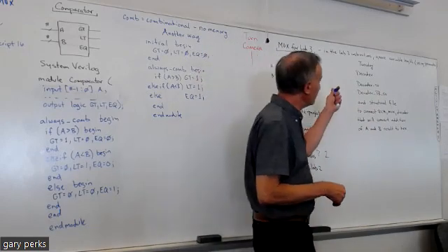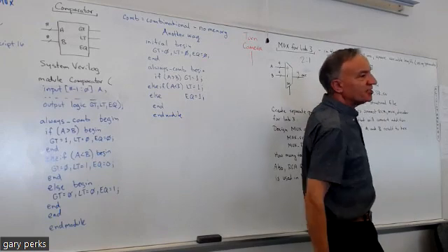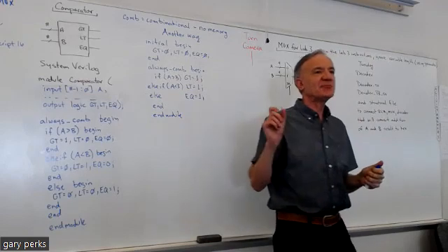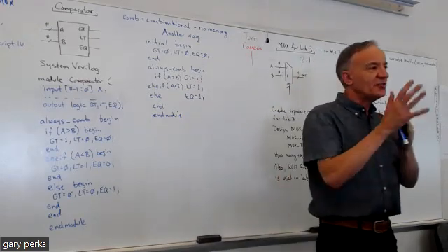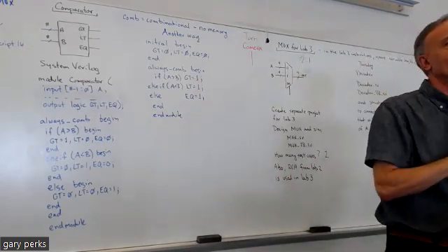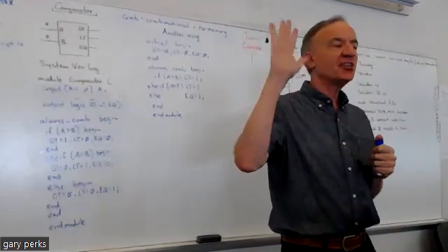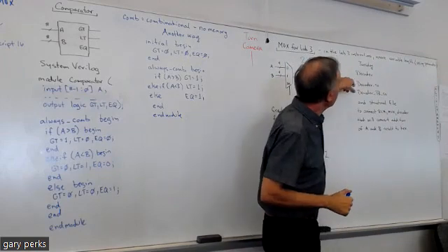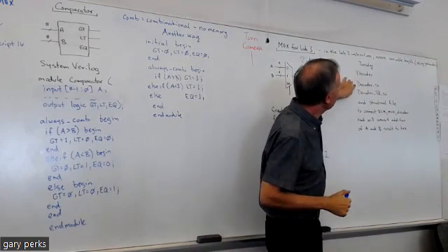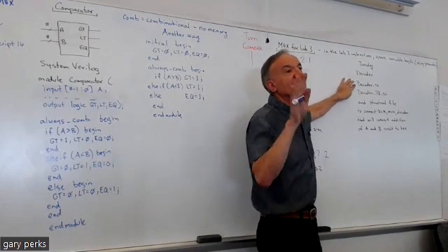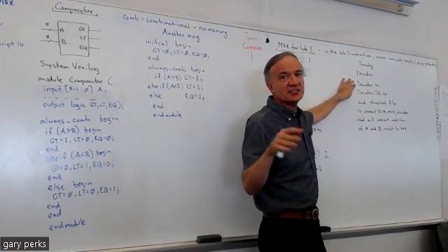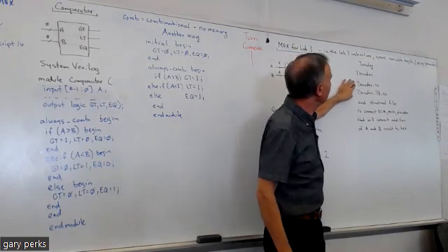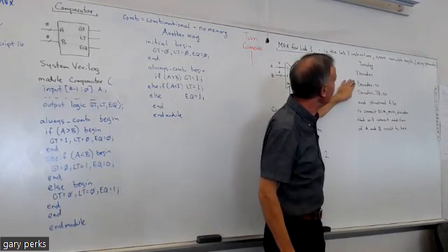And then on Tuesday next week, we're going to talk about what a decoder is. And we're specifically going to talk about a 7-segment display decoder. Okay, on your Basys board, you have 4 7-segment displays. In lab 3, we're going to start using one of those displays. So on Tuesday, after you learn what a decoder is, you'll do a design source for a decoder, and there you're going to use a case statement. Because in SystemVerilog, you can also model with a case statement. So you'll get some practice with a case statement for the decoder.